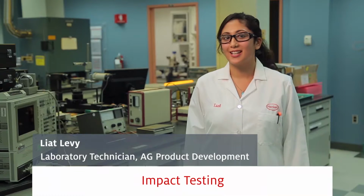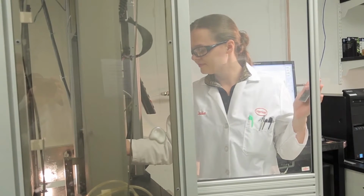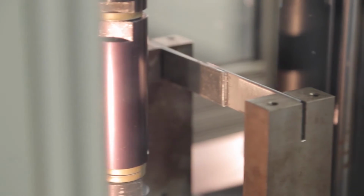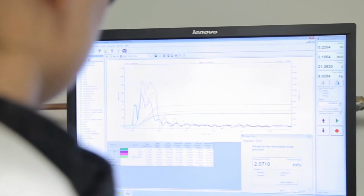Now it's time for impact testing. Impact resistance is a measurement of a material's toughness, which is often a main requirement for components operating under dynamic stresses. This property is highly dependent upon the ability of the material to internally move or deform to accommodate the impact. One way to test for impact resistance is to drop a weight from a set height onto a bonded assembly and then record the absorbed energy.